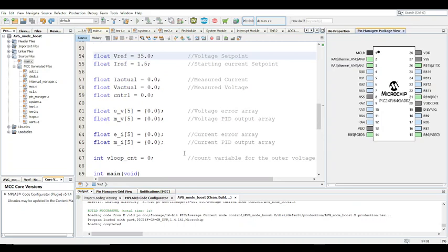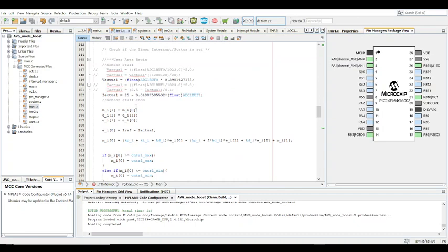This is an average current mode control, which means we're using two sensors at the same time. The current and the voltage sensor, we're using both of them at the same time. The major advantage of this particular routine is that you have inherent current limiting, because you're constantly sensing the current of the inductor and you never go past it.